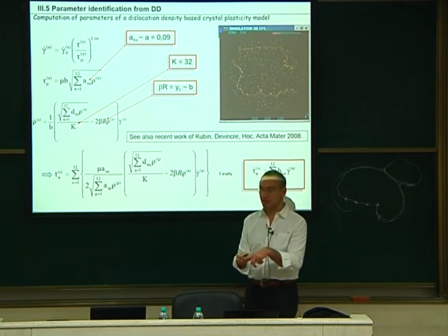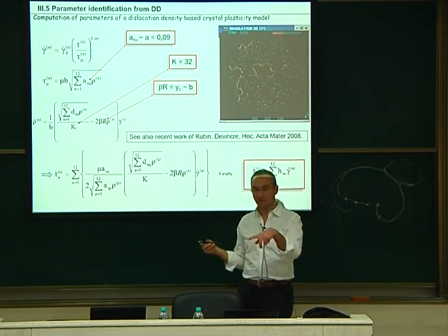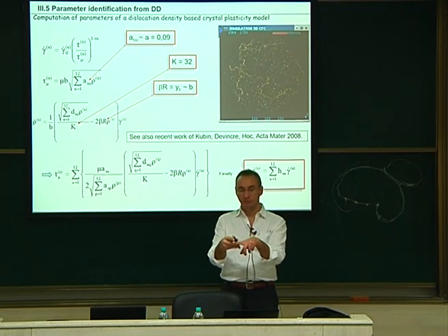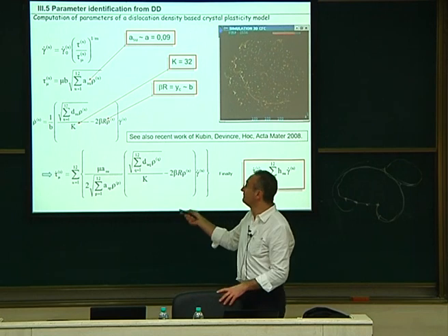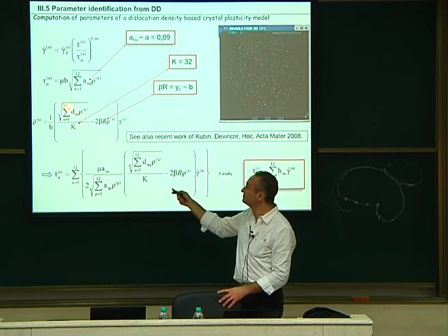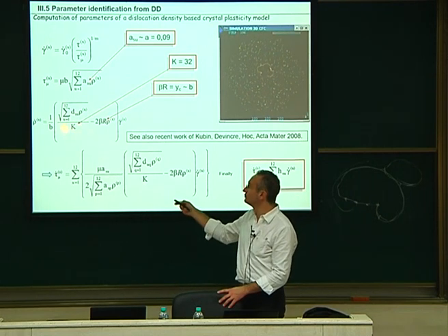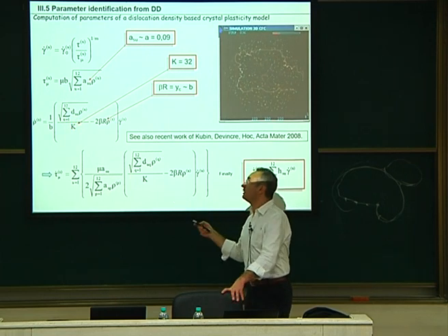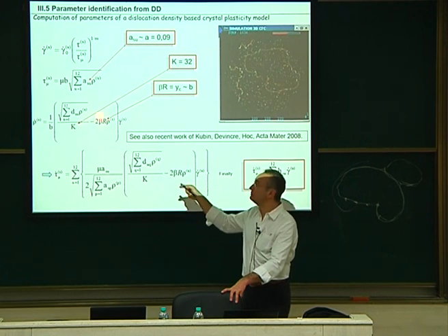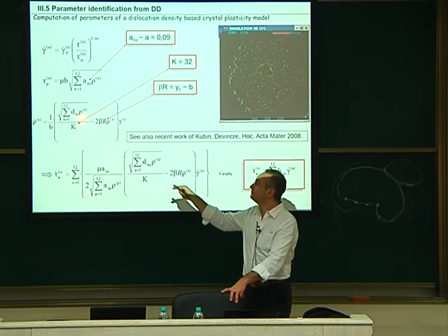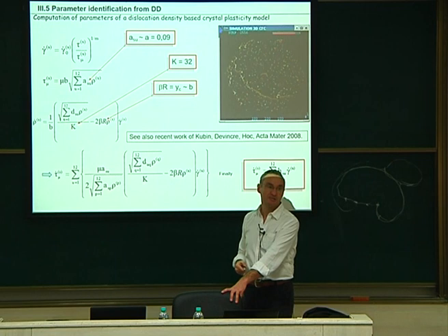I mean that they assume that it's not equivalent if a slip system encounters another one, if a Lomer-Cottrell lock forms, or if it's a Hirth lock which is forming, then K is not the same. You cannot just put a term here. You should also change K. And they also argue that you can add some line tension effect. There is a logarithmic term now in their expression here, which enters into play.